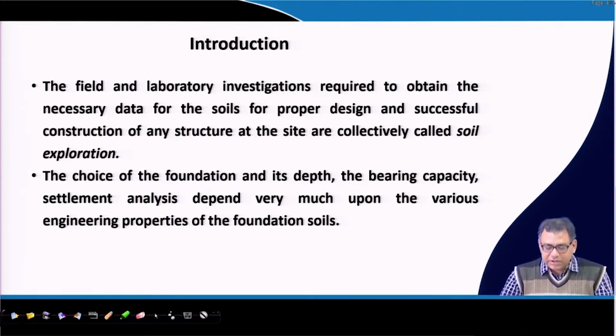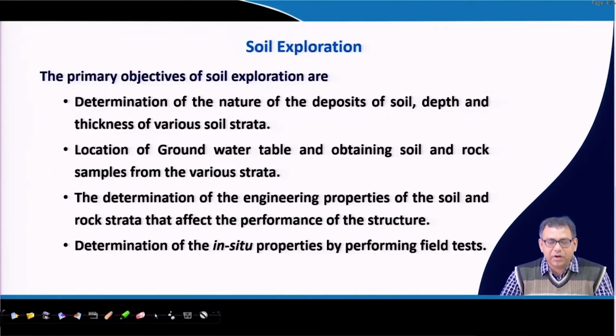The choice of foundation, its depth, the bearing capacity and settlement analysis all depend on the properties of the soil. That is why soil exploration is very important. The objective of soil exploration is to determine the nature of soil deposits, the depth and thickness of various layers, and the location of the groundwater table, which is also very important.